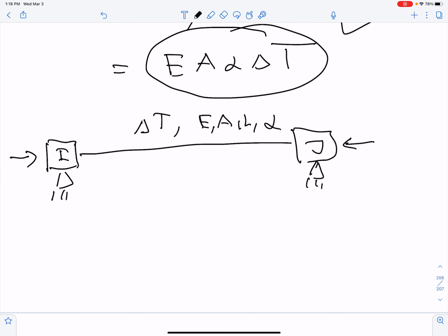And this puts us in the same situation as a distributed load. So remember, when we apply the distributed load, we assume that the nodes don't move, and the distributed load introduced some form of end node forces. So you think of the temperature change along the same terms. Temperature change will introduce the end node forces, and the end node forces, the magnitude becomes EA alpha delta T, and these are distributed in a constant fashion over the bar.